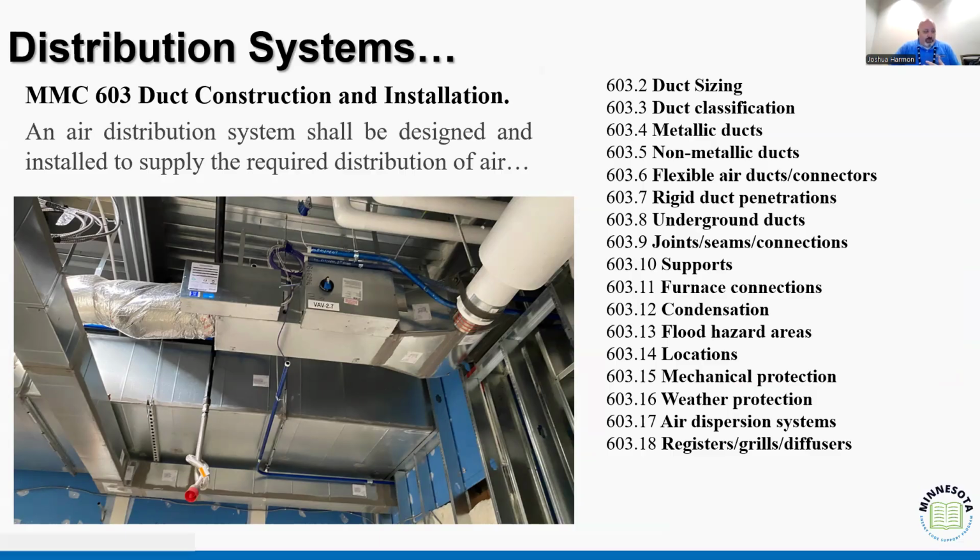When we're looking for controlling condensation, because remember, that's ultimately what we're trying to do, is trying to prevent condensation inside our duct systems because we don't want to be pushing that bad air through our building, right? If anybody's ever had a situation where a panel has gotten dirty or nasty, and I've had this happen in a few buildings I've been in, and they turn on the air handling system, and all of a sudden this cloud of junk goes flying through the air, right? That's because it's a dirty duct. And the reason it's dirty is because we're getting condensation and getting nasty in that area.